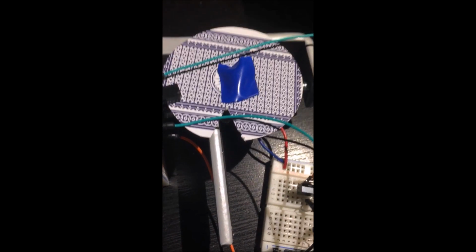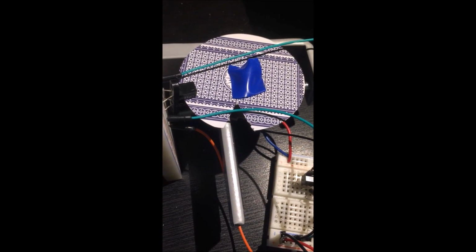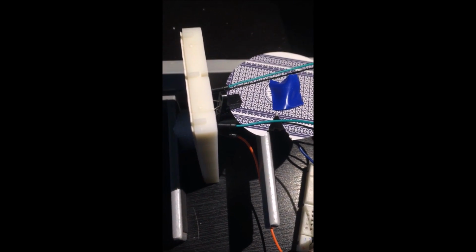Alright, this is my lab video for project 1. The setup, we have 2 clamps, one that holds the motor in an upright position and one that clamps a breadboard with the opto interrupter in it. We have a disc here made out of a playing card with a slit in it, so every time the slit passes through, it'll toggle the interrupt.